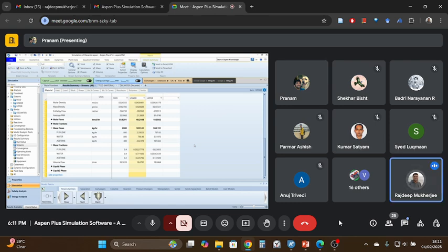Mass fraction is also related in the same way to the mass flows. Actually, if you are using three components and two of them are soluble with each other, then naturally a solution will be formed. But if you are using two immiscible components with a density difference, only then can maximum separation happen in a decanter. Okay, so water and acetone are soluble with each other. So that might be the reason why your result is getting affected.